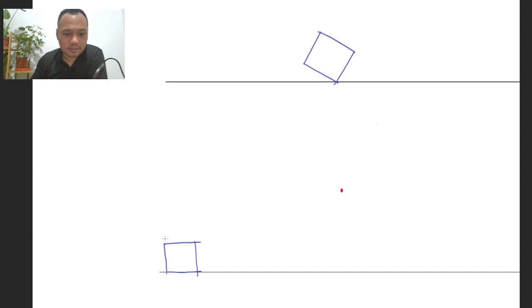And the view line, which will become the horizon line, should be somewhere around the eye level of the observer, which is this person right here, where the standing point is. So we can say that it will probably be somewhere between 1.5 to 2 meters, anywhere between that point. Let's go ahead and do that.